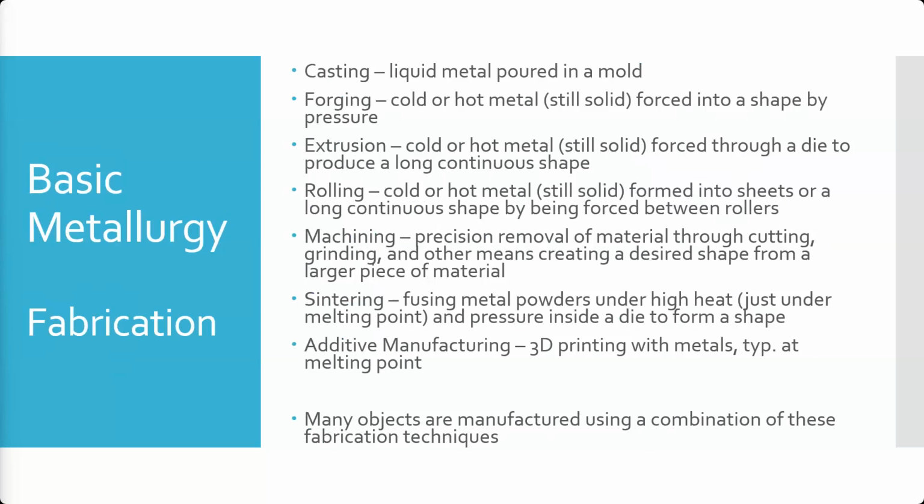A sintered part where it's fused metal powders, you'll pick up that grain structure when you're performing NDT on it versus cast, forged, extruded, rolled, where it's a more homogeneous metal, right? So they're going to react differently. You have to keep that in mind if you're ever designing tests for these, if you get to the level where you're designing tests, or while you're performing tests, what kind of an indication am I going to see? Because that goes back to all of these can cause different non-relevant indications.